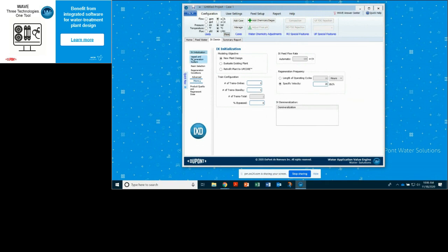Thanks, Garth. And I just wanted to comment on the space velocity here, that typically for working mixed beds, it's between 15 and 30 BVs per hour. But Matt, do you want to comment on applications maybe like UPW or nuclear?